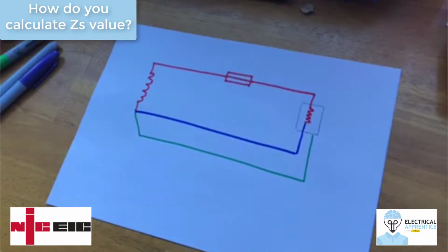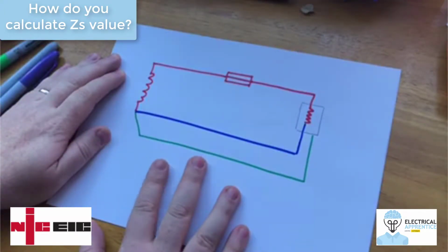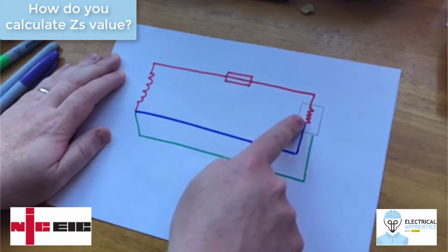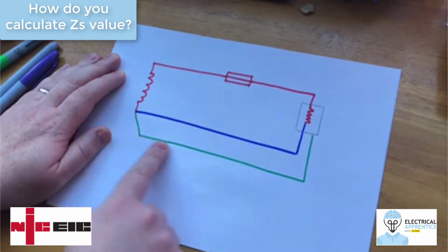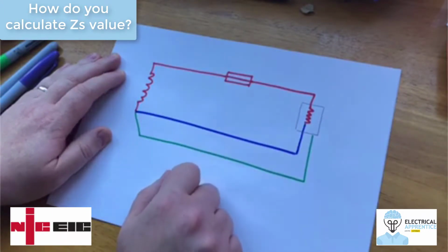Okay, I've tidied the desk, sort of, and as you can see here, we've got a very simple single phase installation. So I've got my transformer coil here, the supply out to the installation, the main fuse, and then it goes out to some form of load, the load neutral back into the star point of the transformer. But also, from the star point of the transformer, I've got the earth that comes out probably to a class 1 enclosure. So you can see that.